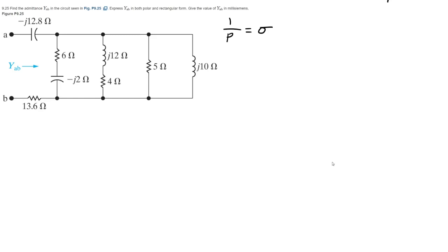The complement here is going to be with admittance. Admittance is going to be 1 over Z. And basically it's how readily a circuit will conduct. Basically, if you have a high admittance, it'll let more current pass for a given voltage, kind of like Ohm's law at a given frequency. So basically we're just going to find the equivalent impedance, and then we're going to take its reciprocal and use that to give the answer to the question.